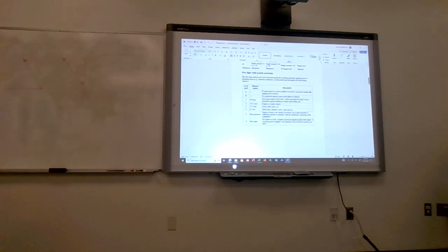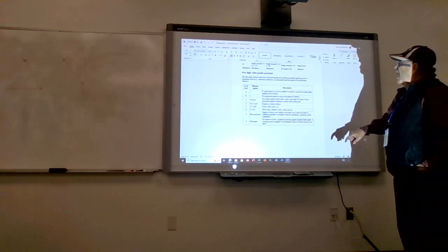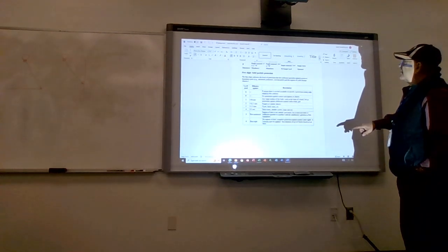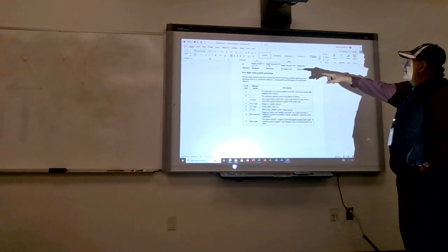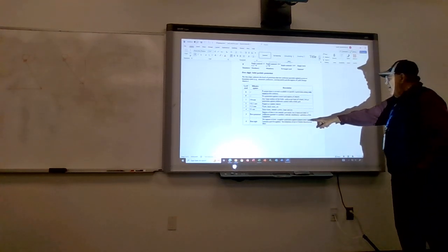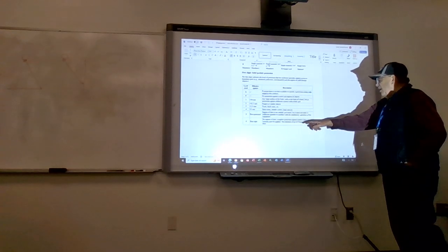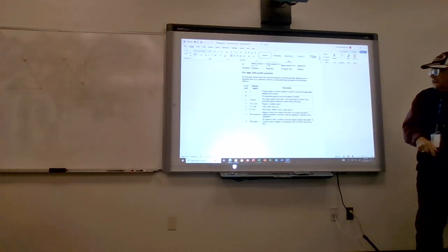Okay, so here they are. IP6: dust tight. No ingress of dust. Complete protection against contact. A vacuum must be applied. Test duration of up to 8 hours based on air.